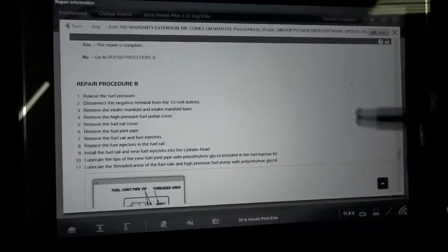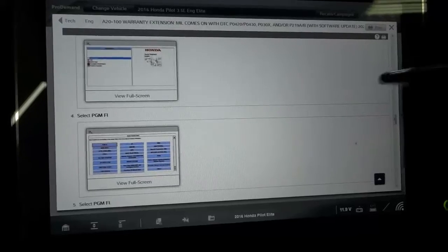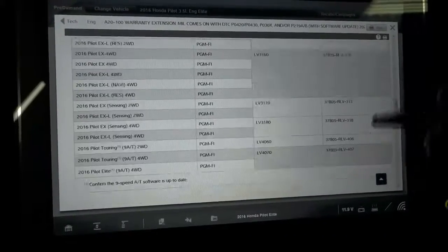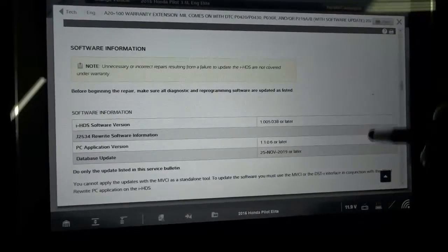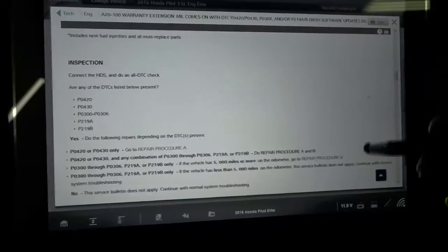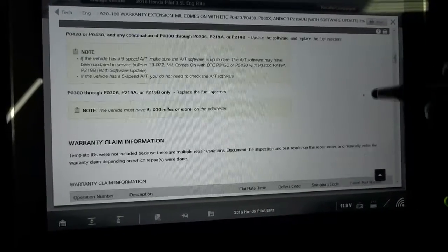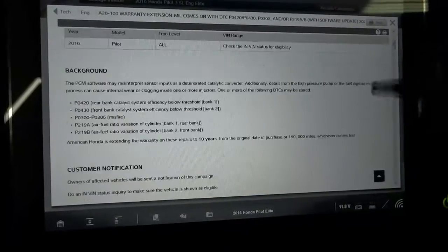So this trouble code can be caused by basically debris, metal shavings or debris, breaking in from the injectors and eventually clogging the injectors. So that's why they're recommending replacing the injectors in this case. So I don't know if we can see that fault electrically, because if we use a lab scope, the lab scope will most likely just show us the electrical fault.